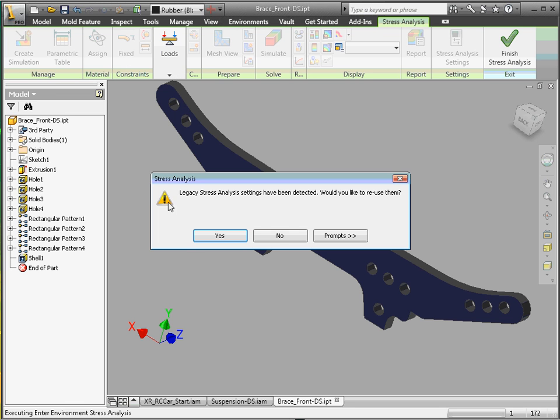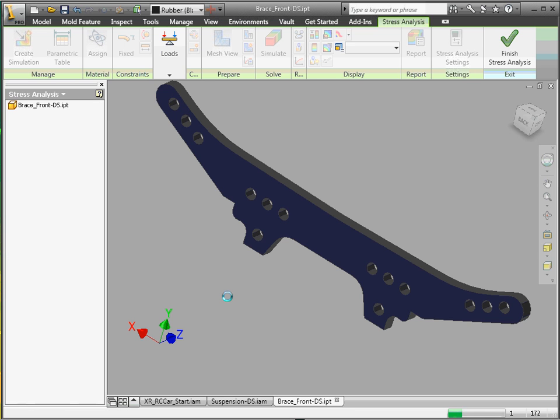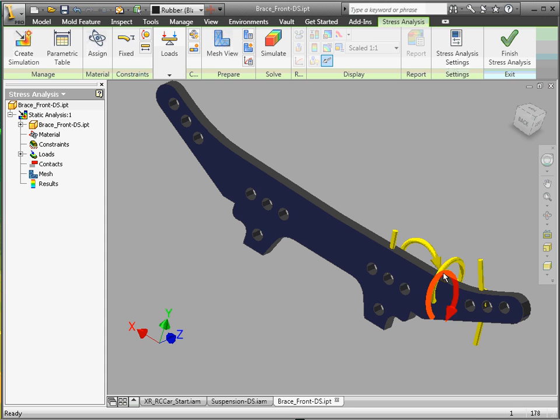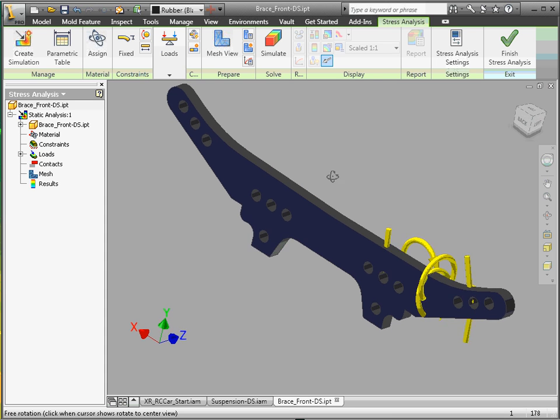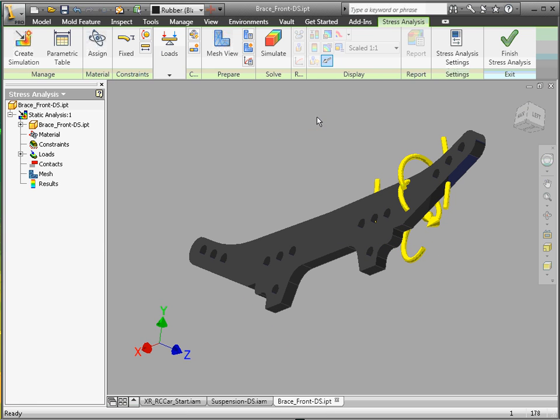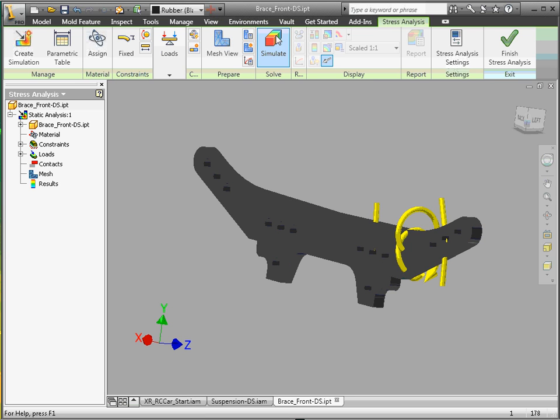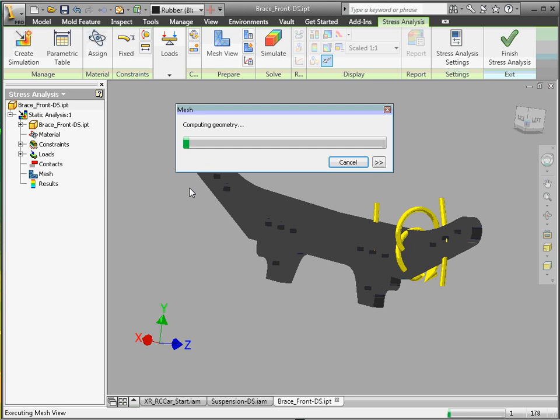Now we've done all of the forces in the component via our motion simulation. So what we can do is tell Inventor to add those loads automatically into the part. Now you can see all of the loads have been added. The only thing I need to add, because I've opened this in its own environment, so it's not actually fixed down to the other components, is I just want to say I want to fix these two faces here. So it's just got something to push against.